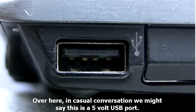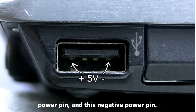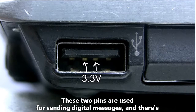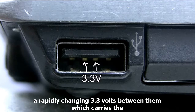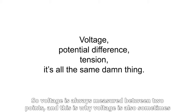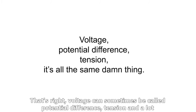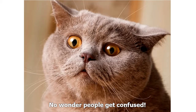Over here, in casual conversation, we might say that this is a 5-volt USB port. But what we really mean to say is that there's 5 volts between this positive power pin and this negative power pin. These two pins are used for sending digital messages, and there's a rapidly changing 3.3 volts between them, which carries the information. So voltage is always measured between 2 points, and this is why voltage is also sometimes called potential difference. That's right, voltage can sometimes be called potential difference, tension, and a lot of other names. No wonder people get confused.